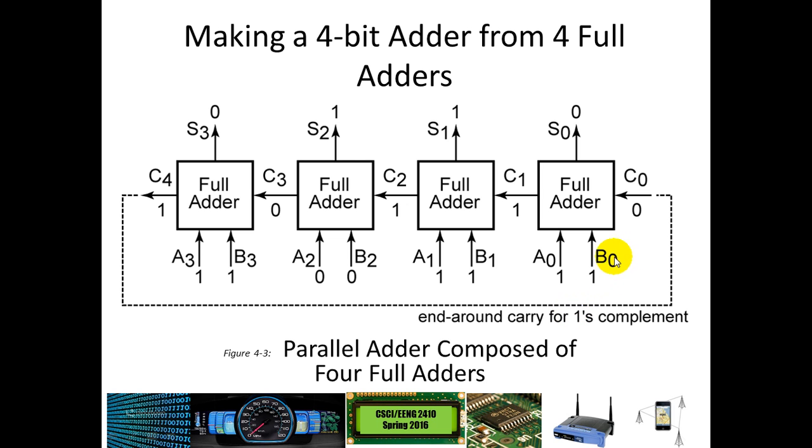So here's an example here. If I were to add these 2 values together and I had a carry in, let's suppose our initial carry in is going to be 0. So if we add 0, 1, and 1, that gives us a sum of 2. And so 2 is 1, 0, so we put down 0, that's in our least significant place, and then we put our 1 over here as the carry out.